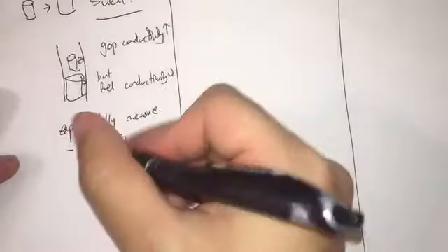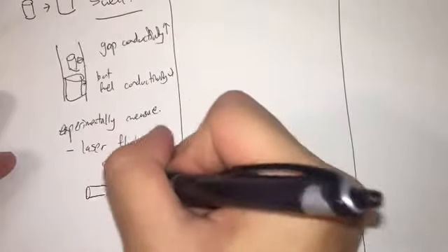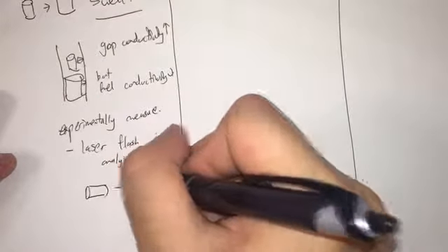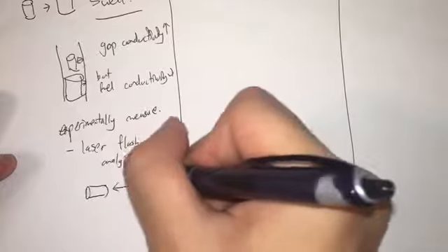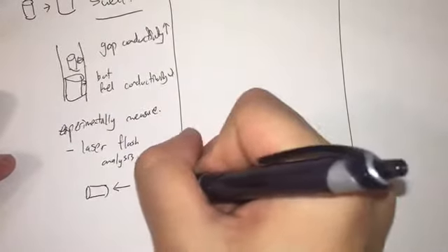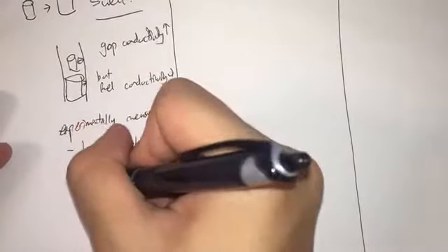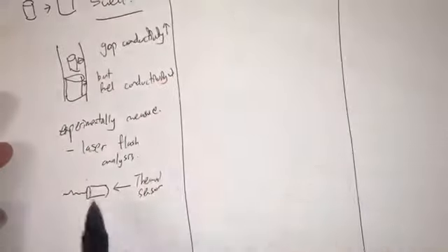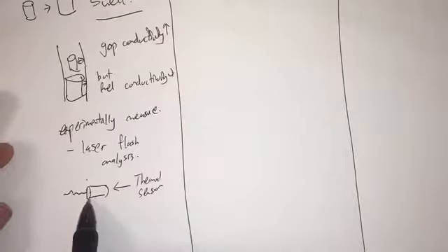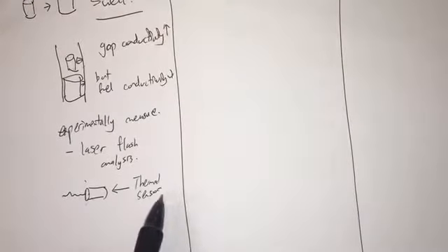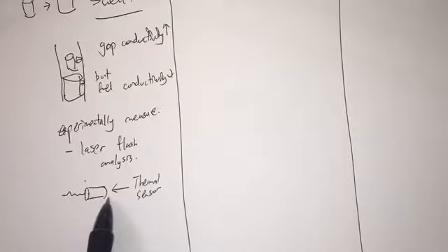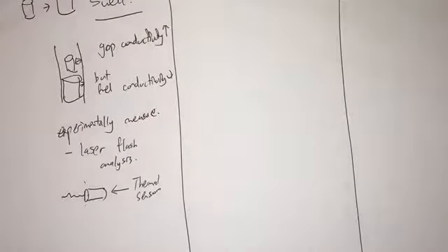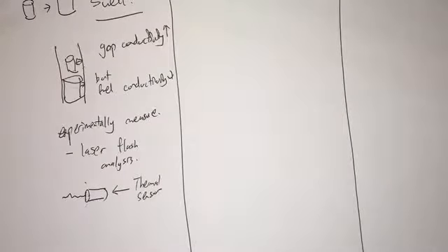Okay, so basically they'll have a sample of fuel here. There'll be some infrared or thermal sensor here. And then a pulse of laser will be directed to the opposite side. The thermal sensor will see how long it takes for the temperature here to increase, and that will be telling of the thermal conductivity of this fuel element.